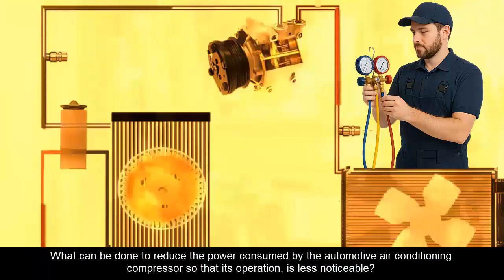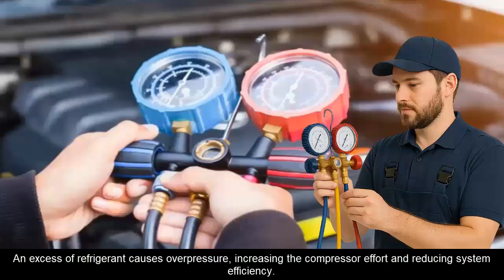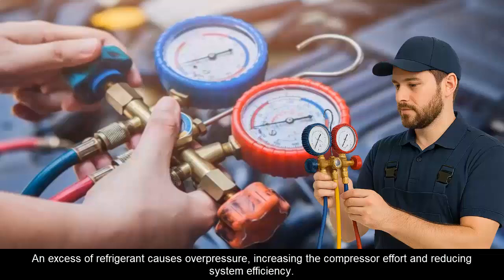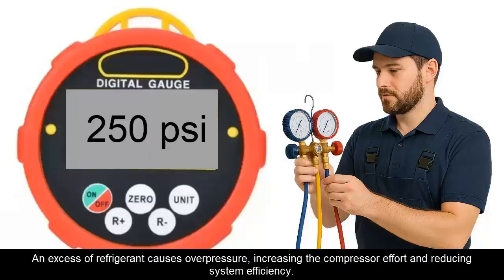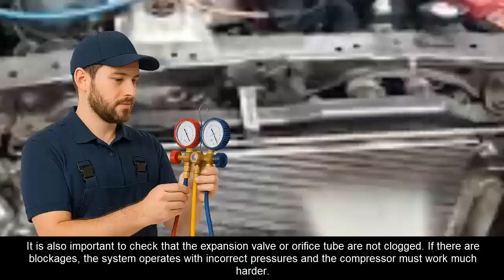What can be done to reduce the power consumed by the automotive air conditioning compressor so that its operation is less noticeable? 1. Check the refrigerant gas level in the automotive air conditioning system. A low level causes the compressor to run constantly, which means higher energy consumption and lower cooling capacity. An excess of refrigerant causes overpressure, increasing the compressor effort and reducing system efficiency. It is also important to check that the expansion valve or orifice tube are not clogged. If there are blockages, the system operates with incorrect pressures, and the compressor must work much harder.